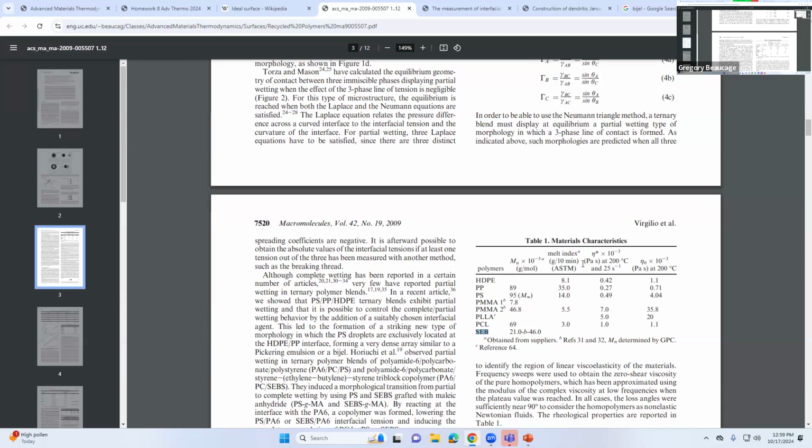So polymers have shear thinning behavior. For a polymer, you plot log of the viscosity versus the shear rate. So basically, usually you have a plate and plate, and you're spinning this at some frequency. That frequency gives you the rate of strain, like d strain, d time. And then there's a torque involved in that. The torque making it spin is kind of a force, and force per area gives you the shear stress,